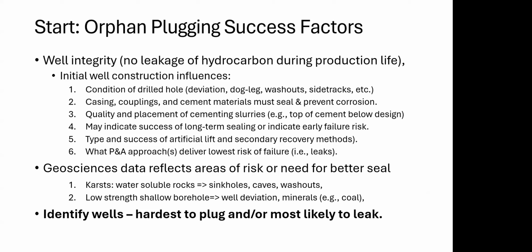Now, casing, coupling, cementing, talked about a little bit. The quality and placement of cement slurries, I'll keep coming back to that over and over. That is critical. Now, it may indicate success of long-term sealing, and we're talking about the cement. This is a well I'd worry about less than any other well. Now, the type and success of artificial lift and secondary recovery methods, those are factors, but they factor in well down the road. So find out what P&A approaches have been used and how diligent the company was in